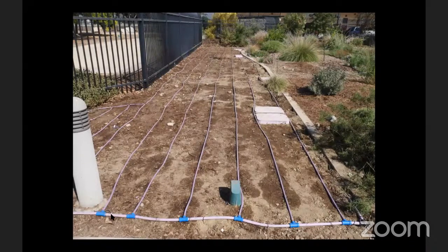But for the header here, instead of using PVC, we use for this situation a product called Blu-Lock, which is an alternative, which comes in a 3/4 size. It can put the amount of water through as a 3/4 line. It's a little more flexible than PVC. It's made out of polyethylene. It's basically thicker walled and more rigid than drip and larger. It does have fittings with a little gasket that just push together instead of having to glue it. And it's just a little faster and more environmentally friendly.